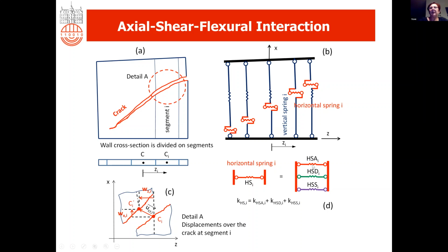Actually, the aggregate interlock, the dowel effect, and the effect of the shear reinforcement. So they are connected in parallel, and then they define the shear stiffness of each of these springs.